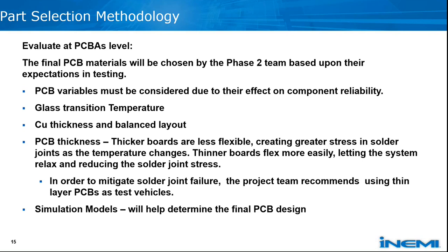We'll also need to consider the surface finish, the layer count, and we'll need to have a solder mask that will be able to endure the conditions that we plan to put them through. We don't want it coming off before we finish our tests.